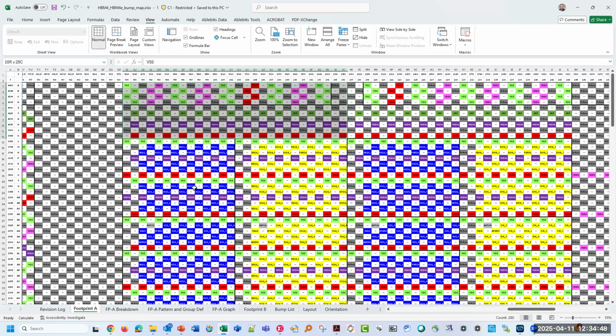And then what happens when you have different manufacturing processes that could lead to a different Z height? And I think for that reason, you said don't put in Z dimension in the form of millimeters. You said put it in the form of index, as in this die is in this position 0, and the next die on top of it is in position 1, and so on all the way up to the top.